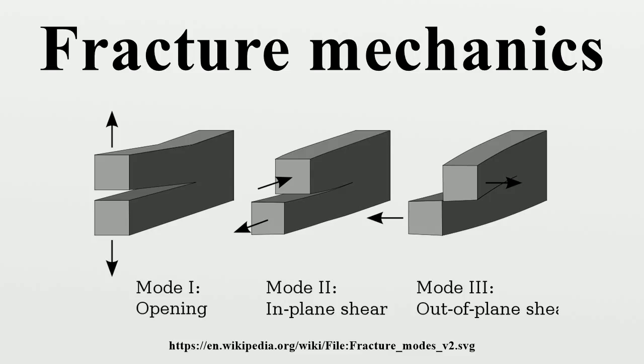However, this assumption is quite restrictive for certain types of failure in structural steels, though such steels can be prone to brittle fracture, which has led to a number of catastrophic failures. Linear elastic fracture mechanics is of limited practical use for structural steels, and fracture toughness testing can be expensive.